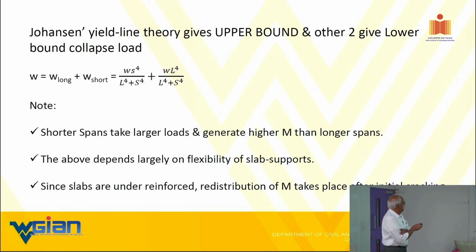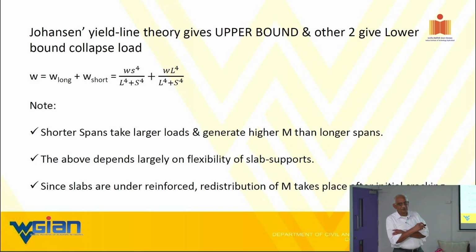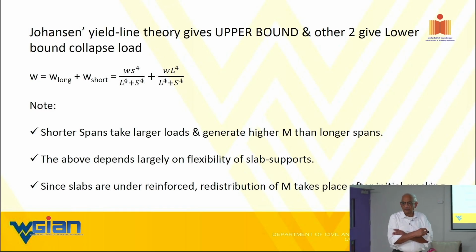So why I gave that pitch is because the short span takes a larger load and generates higher moments. That is why I made that statement. Some guy, I'm not going to say a whole lot about who, what, where, said, "Sir, come look, I designed this building."